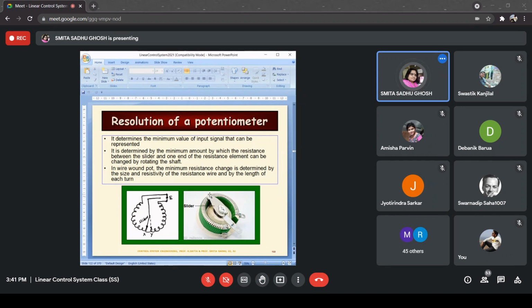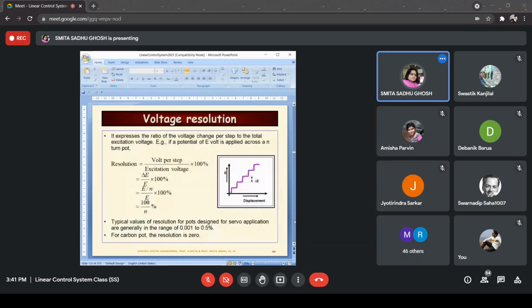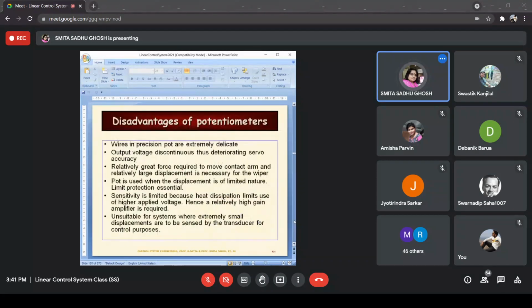The amount of force that is going to be required to move it is going to increase, because this is being pressed against this one as per construction, and I have to move it. So basically, that is a problem. It means that if it is used in some delicate application where that much force is not being generated, then the slider will not be moving at all. So that is a limitation or disadvantage that we would be having.